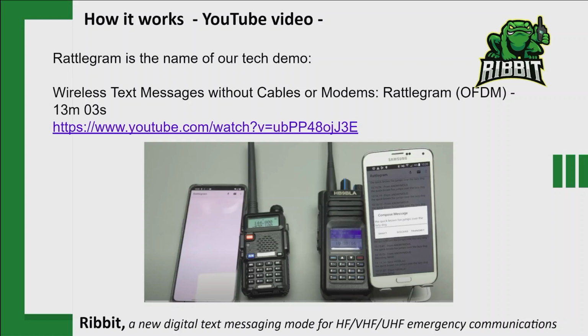In the About box of the Rattlegram application on Android, it says a prolonged exposure to the ultrasonic sounds. Do I have to worry about my dog? No. That's only when you use, because in this test demo, we open up all of the parameters to the codec. If you stay on the 1600 bandwidth, you don't go into high bandwidth, 48 kilohertz, it's not going to go into high frequencies. I'll show you on your phone which setting is going to go into ultrasound. But in the Ribbit app, we take all that away. We already know which modes and configurations are the most efficient, so there'll be none of that complexity.